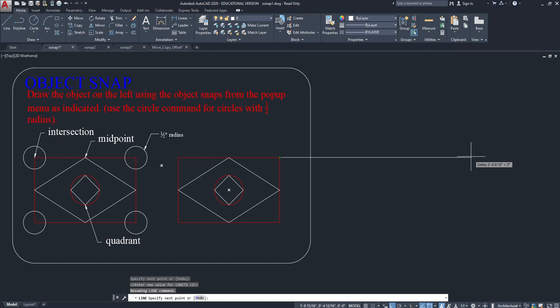of course I could click to end this line. I could move this out to where it says 8 inches. Ooh, it's getting close. 8 1/4, 8 3/16, 8 1/8, 8 1/16, 8, right? I could click right there and I could get 8 inches. But that's kind of a pain in the neck. You don't want to be doing that while you're drafting along, right? It's not quick. So a better way of going about that would be to input 8 inches. Click to initiate your line command, move in the direction you want to go, and I'm going to type 8, enter.